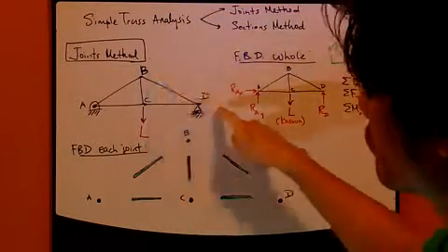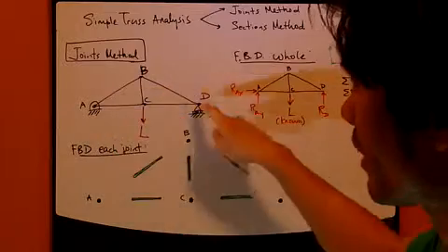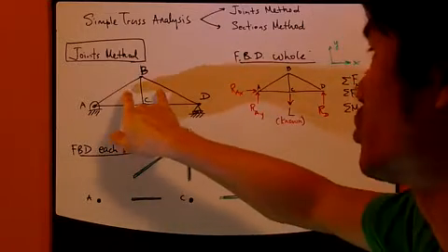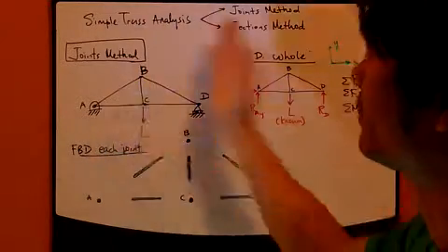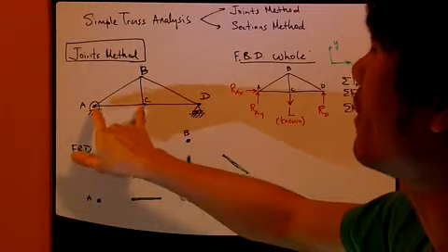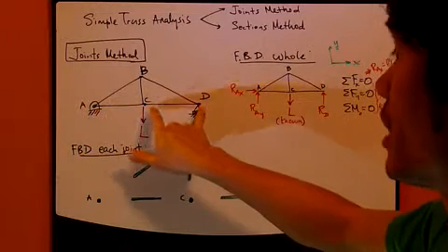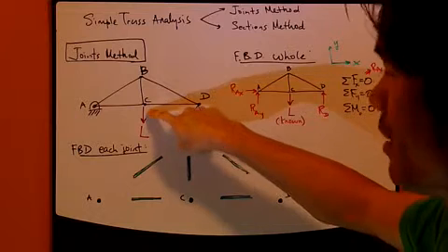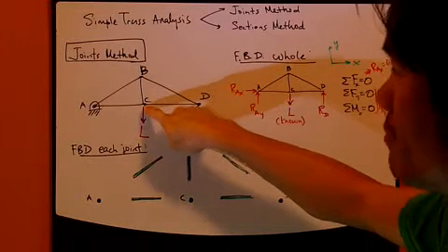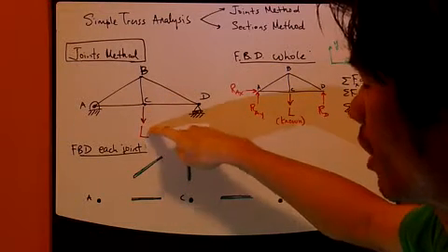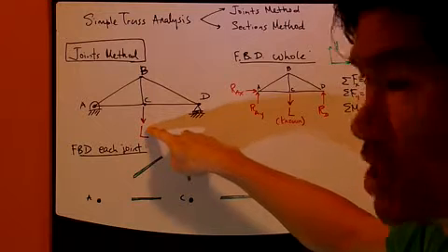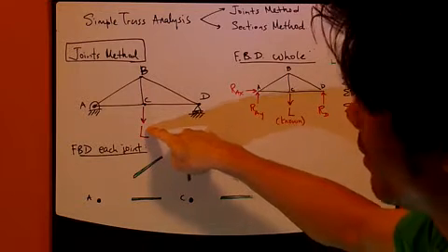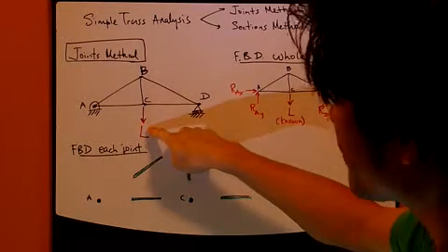So I have this truss that's shaped like this that consists of sort of two triangles, and that's symmetrical. So this AC has the same length as CD. I have this applied load down the middle at joint C. So we're going to call it L. L is a known quantity. It's a force, right?